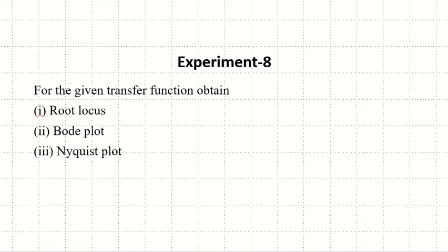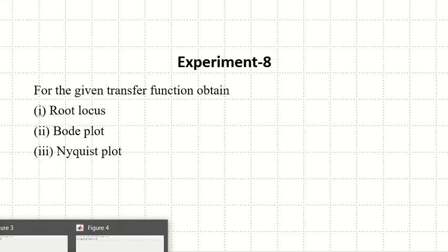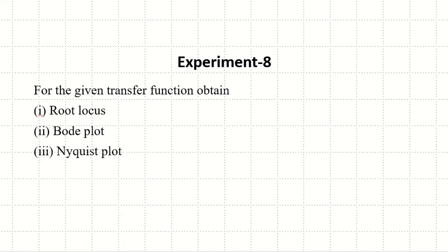So let us first of all assume a transfer function, and we'll start with root locus. There are commands for root locus, Bode plot, and Nyquist plot. I'll discuss each of them, and they are very easy. In short, the command for plotting root locus is rlocus, and within the braces you write the transfer function.